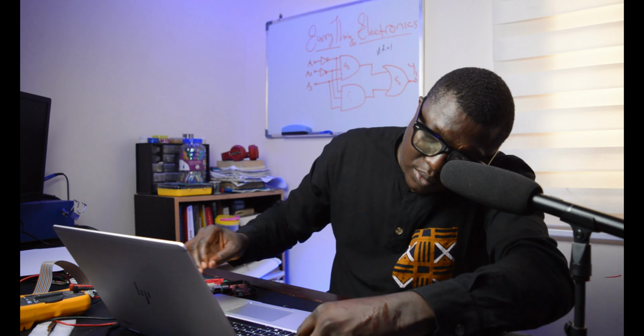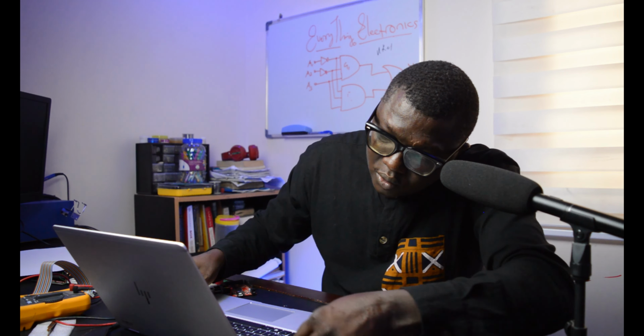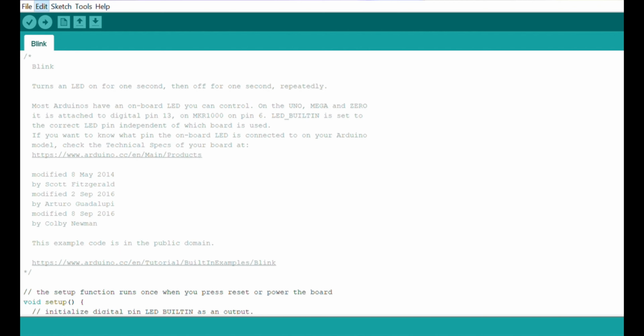Once you open the IDE, you connect your Arduino, and once you connect it, first of all, you go and select the board. So we are using Uno. You select the board, then you go back to Tools and check the COM port. Here we are using COM8, which is the Arduino Uno. So COM8 is Arduino Uno.